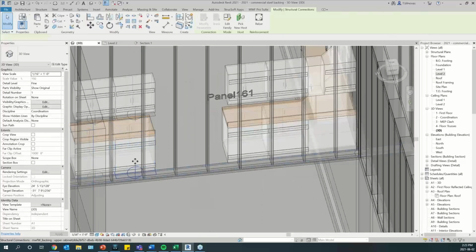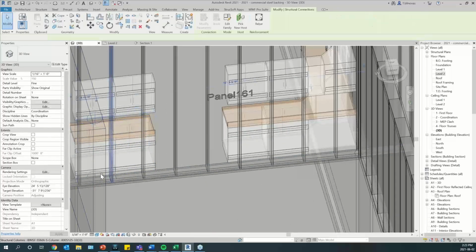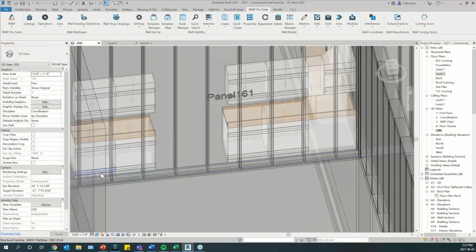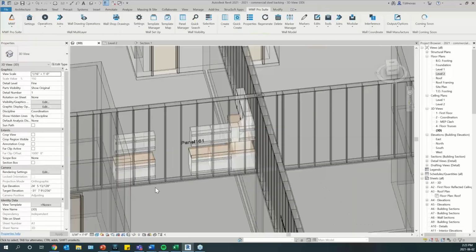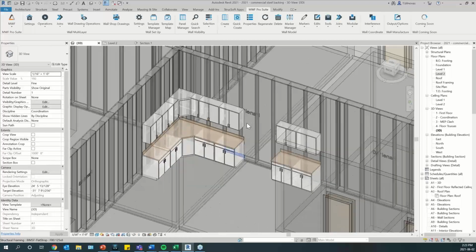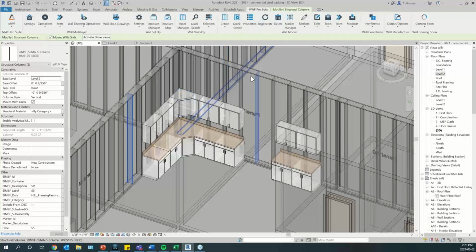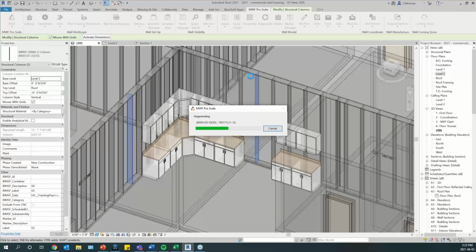Just like any other marker, for example, extra verticals, if you delete the marker itself, once you regenerate your panel, you're not going to see those members anymore. So right now, if I just regenerate, I'm not going to have any backing members anymore.